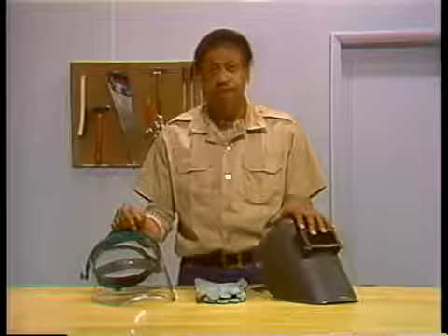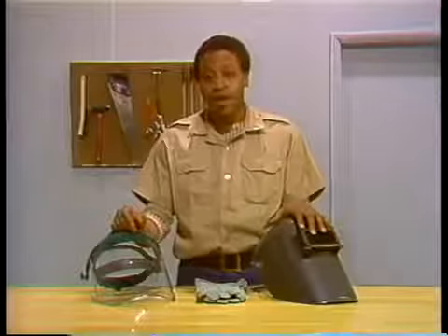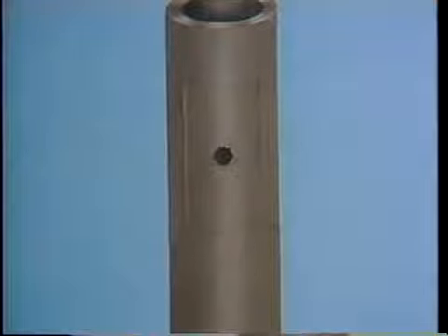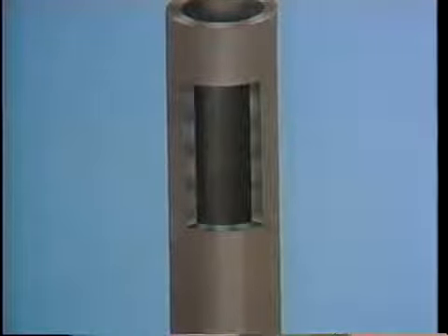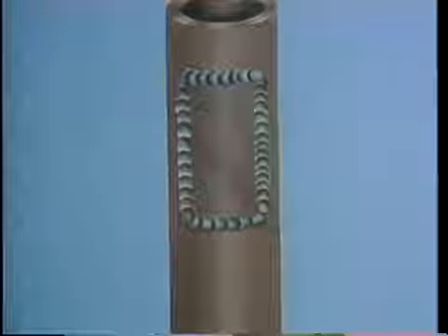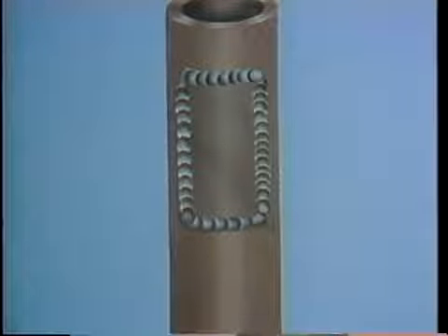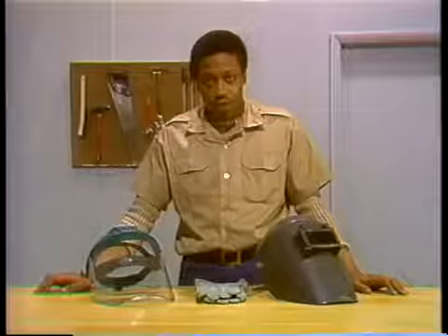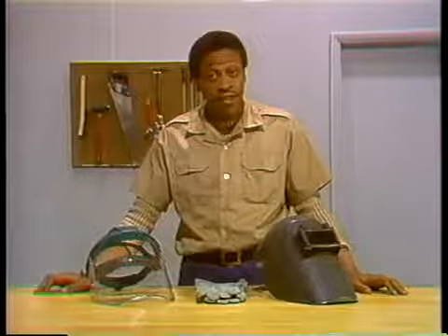Let's continue our discussion of boiler tube repair by going over the window repair method. In this procedure, the failed area is cut out of the tube and replaced with a new piece of the same shape. As you can see, the area that is cut out looks something like a window. Window repairs are more difficult and time-consuming than closing a rupture.